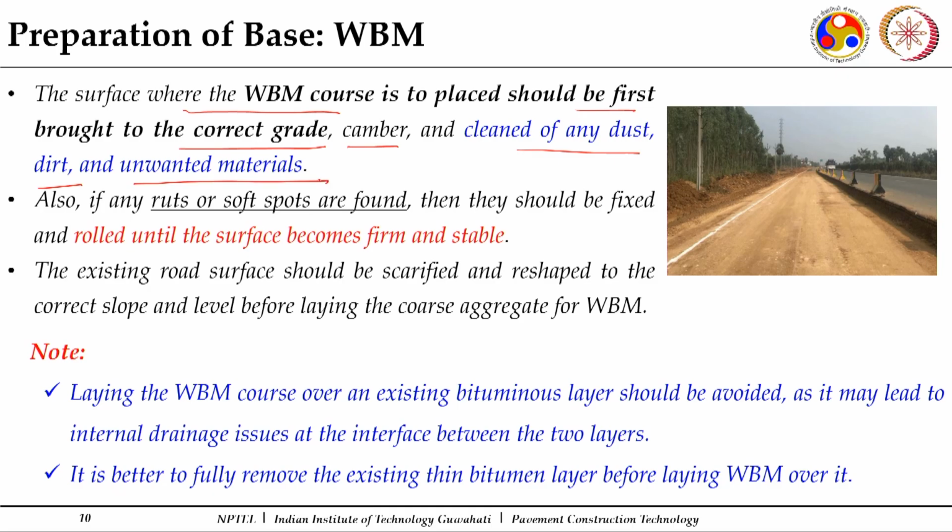So, it should be ensured that when you are putting up the next layer, the existing layer should be in a proper manner, in a good foundation state. Also, if any ruts or soft spots are found, because if there is rain, at certain locations if standing water is there, it will make your material soft.